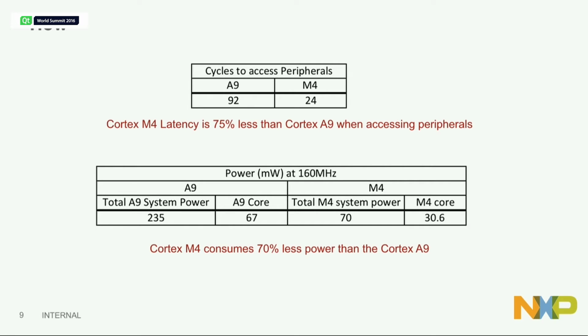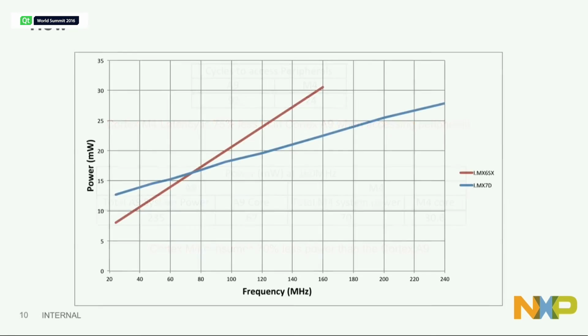Next one. This describes the power differences. Just looking at this, I think it's interesting, it tells a lot, this picture. This blue line is in 28 nanometer. This red line's in 40. The slope means the process difference, because the capacitance of 28 is significantly less than 40, and power goes as 1/2 CV squared. So you can see the difference in process.